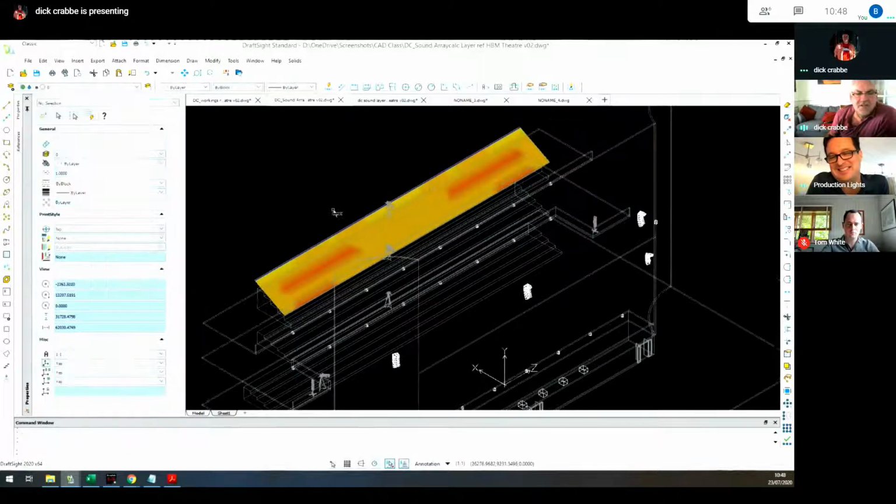So this is the heat map of loudspeaker coverage. D&B's ArrayCalc will allow you to export them as a PNG, which you then stick into Paint, turn into a JPEG, crop them down, and with a little bit of messing around with scaling, you can drop them back in. That is an image that is XREF'd into the plan, and it sits there as its own little layer.